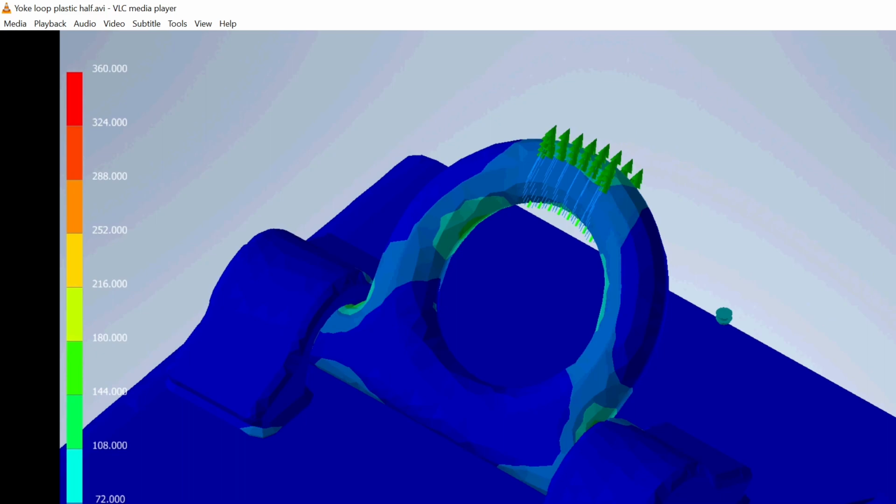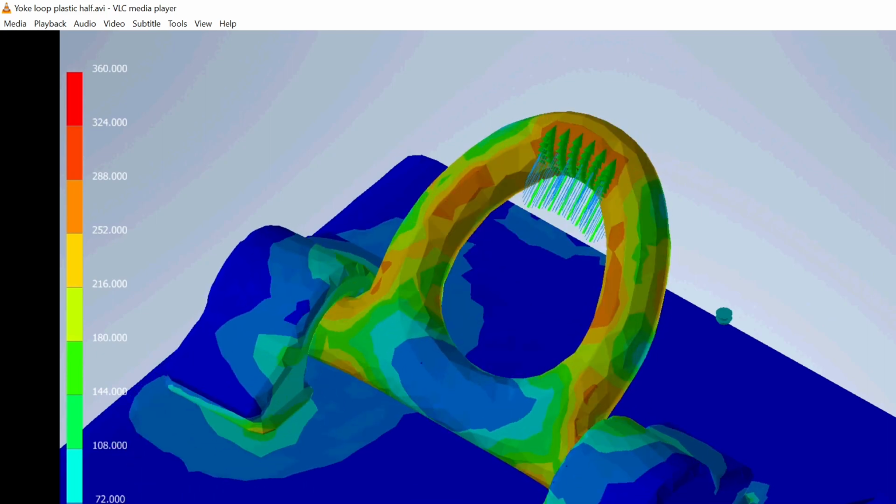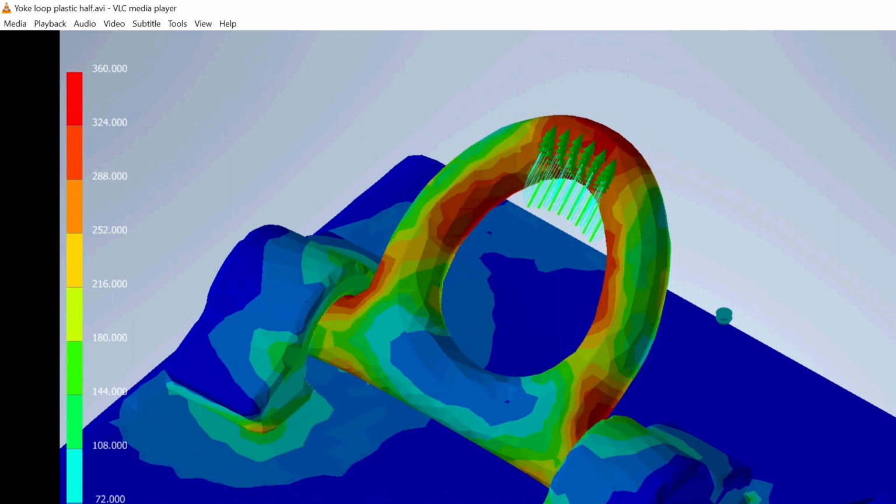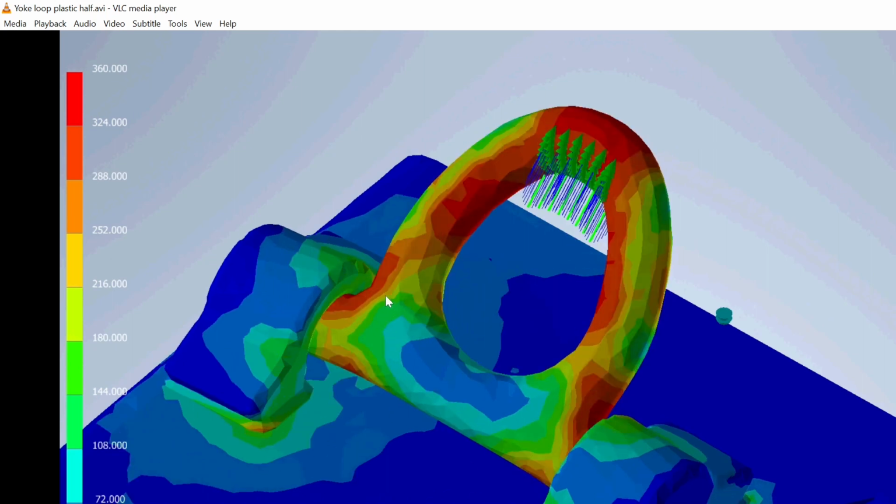So I just thought this is an interesting example. I want to share it because it shows some very fancy modes of failure where you can have a pull through, you could have a failure in tension. There are some contact points with high stresses near them, so potential slip of a leg out, and a small corner of a weld with a concentrated load, which is probably okay. The welds could be made a little bigger, and this is just the minimum size that I've looked for.